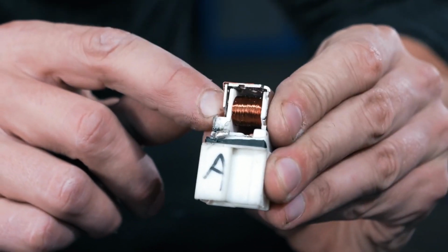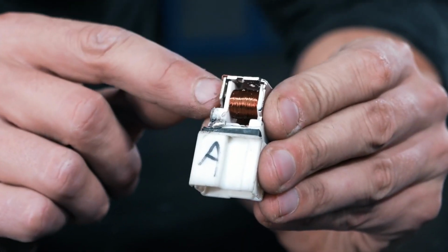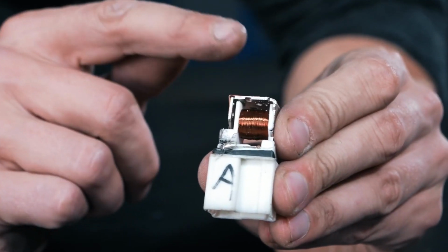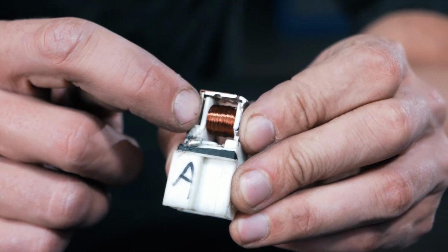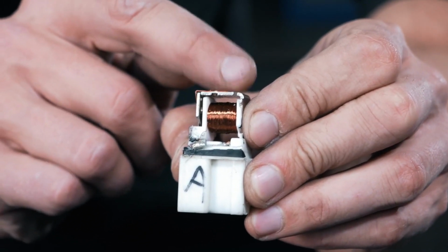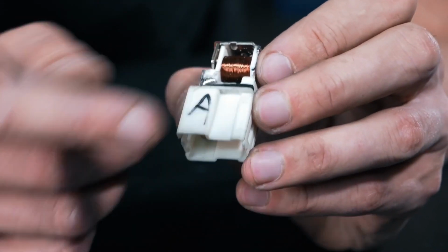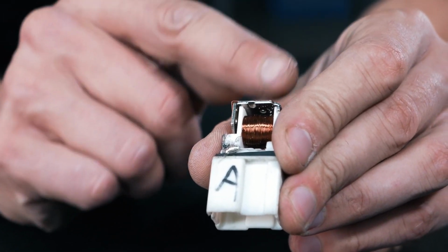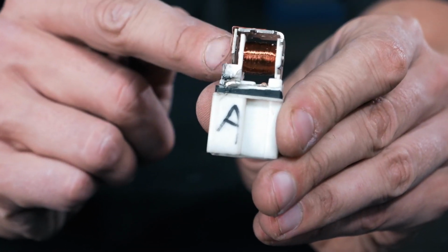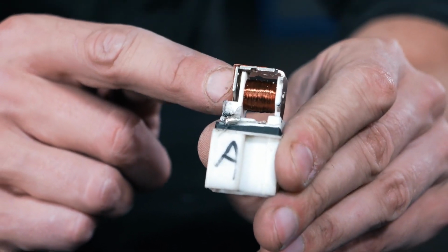Now, first off, what we can see is that we've got things inside here that actually physically move. This is an electromechanical relay. That means it uses electricity and mechanical movement. And wherever there's mechanical moving parts, there's scope for failure. So there's an electromagnet here, which is turned on and off, in our case by the ECU, which is controlling the fan. And the ECU, or the input current here, comes into this coiled wire here, energizes this electromagnet and pulls on an armature here just at the end.